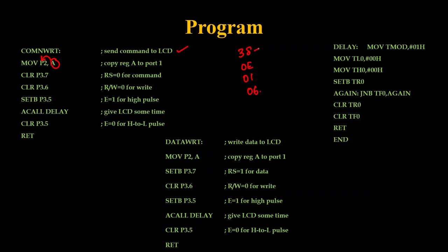If it is 38, the 8421 combination, right? 0011, and 8 is going to be 1000. So it is going to have 8 bits, right? These 8 bits will reach your data pins D0 to D7, so that it can be understood, yeah, 38 is coming, but it doesn't know where to store. It is going to reach your command word, or it is going to be your data word, but it is going to send data. So data will remain there.